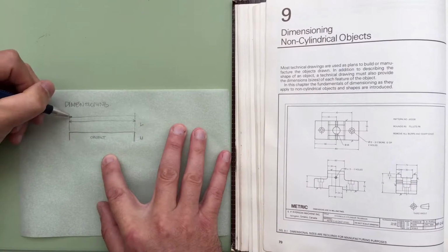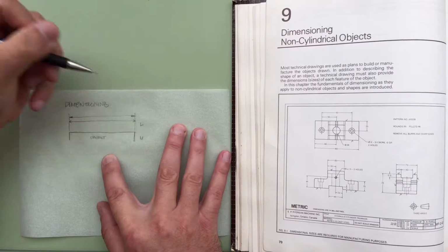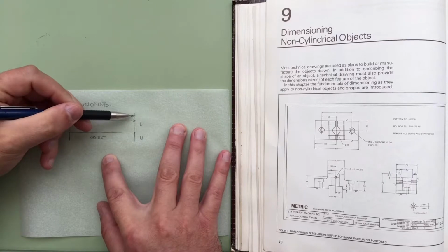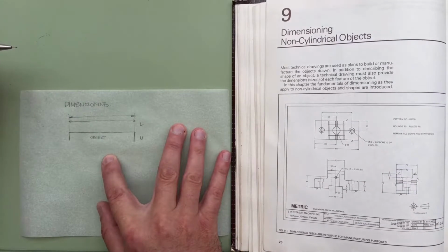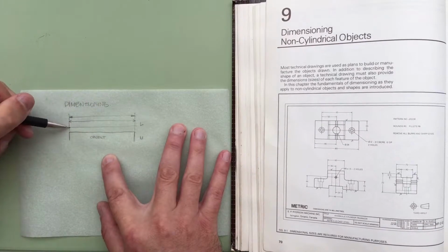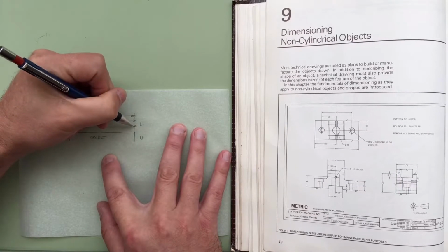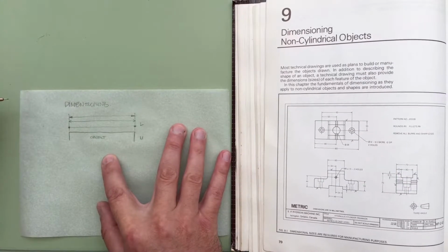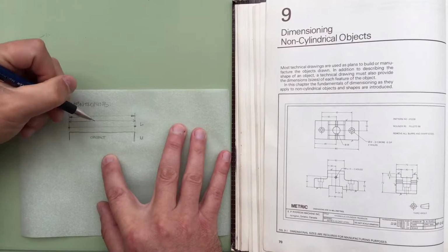What I mean is they'll fill it in, but it will not enclose as large an angle. So you can see the arrows here that are filled are quite tight. Another option that I have seen used in the past is to just use a dot, and all three of those are acceptable. So whatever this dimension is, you've got options here as well.